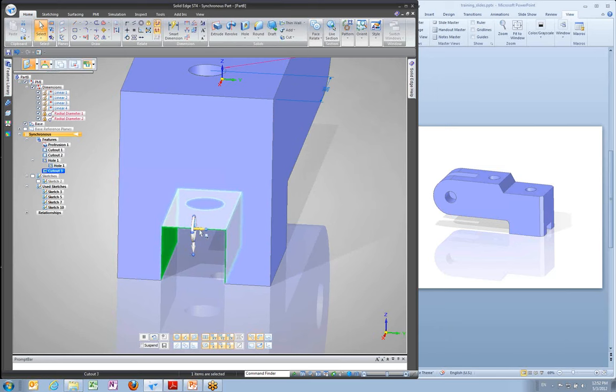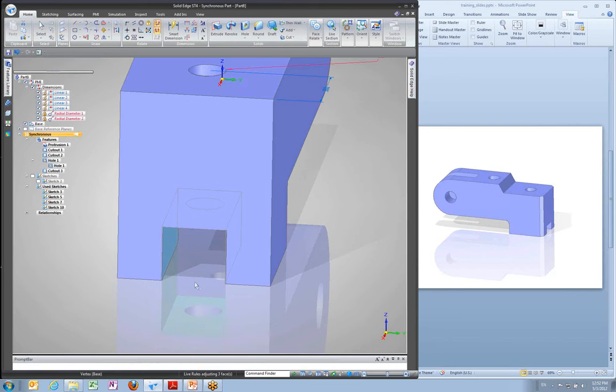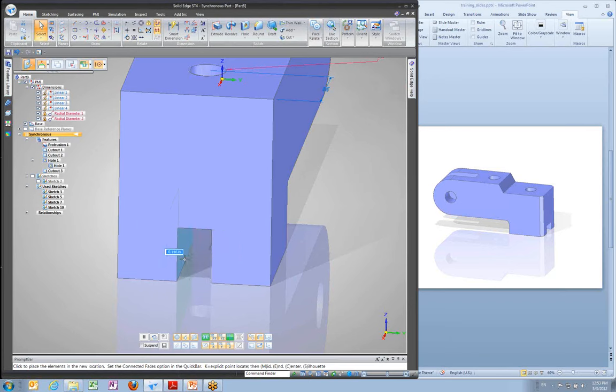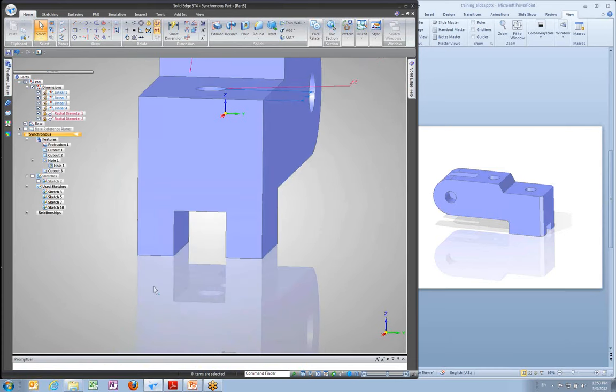And what I can do now is click on that minor axis and start a move, and that's sliding it back and forth. Now because I've picked up on the center point, all I have to do is find some feature that's on the center, in this case the origin, and click and place it. And what that's done is centered the midpoint of this onto my origin. And the result of that is now a symmetric relationship.